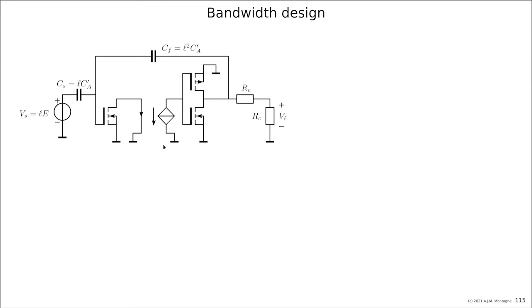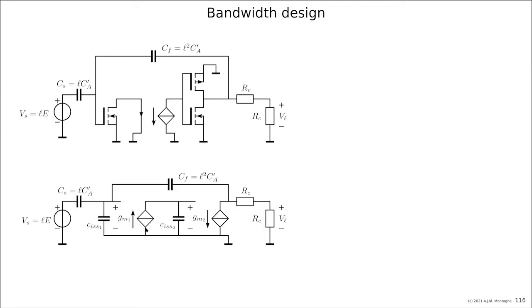So let's go to the small signal equivalent diagram. The current mirror, the inverting current amplifier, is drawn on concept level here. It shorts the first stage and it drives the second stage with a current. So basically I can replace the whole thing by just swapping the sign of GM, keeping a simple model. So now I have inversion in the loop, you see.